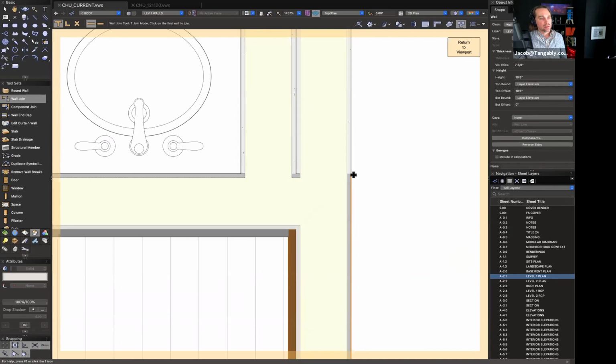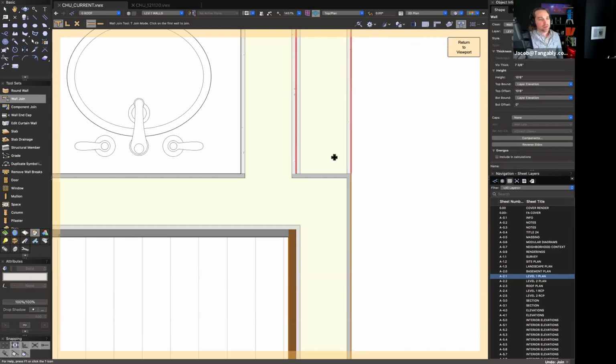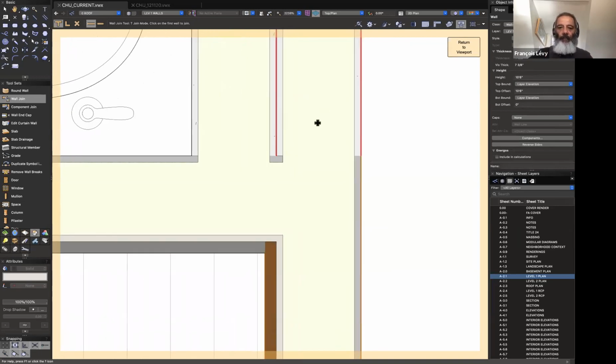If you tried to do a join with the horizontal exterior wall, it would tell you that the walls don't intersect because one sticks out further than the other. Right. And so that's where that sort of parallel, it's counterintuitive because you don't think of a T-join as being a parallel join. Right. But the T-join also works on collinear walls. Nice. And that can be useful sometimes.